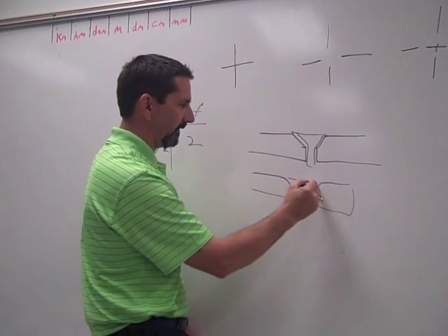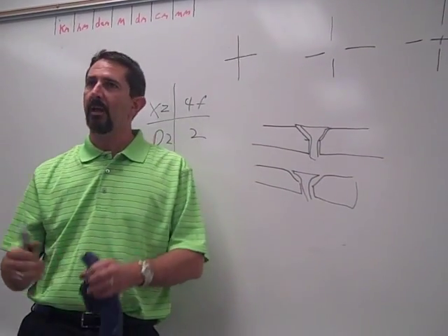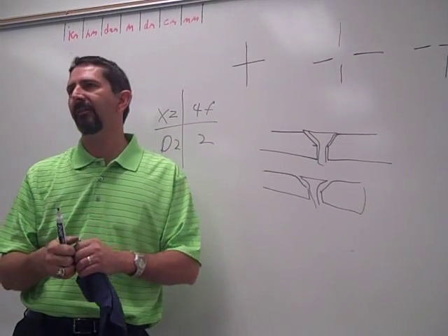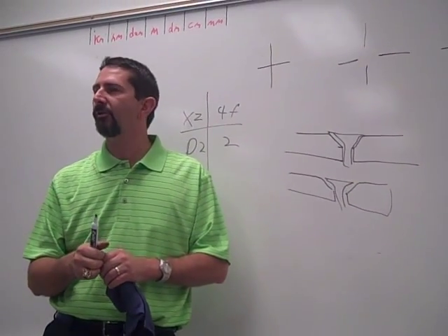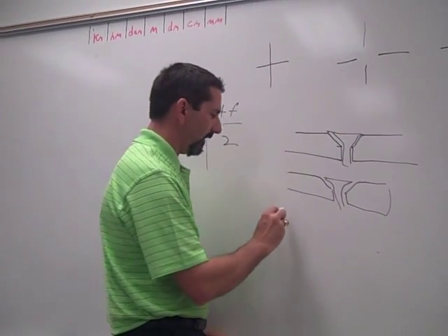For the fastener to rest in the hole. It does exactly the same thing without removing the material. Dimpling will harden the material, and you usually see this on thinner material that is too thin to countersink. Some material can't be countersunk. We also have a counterbore.